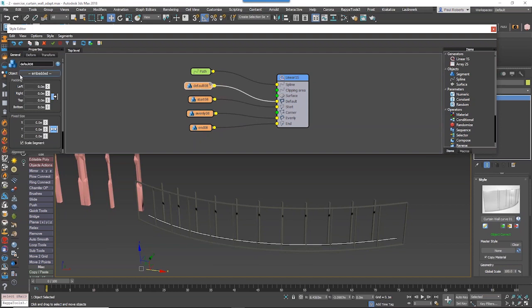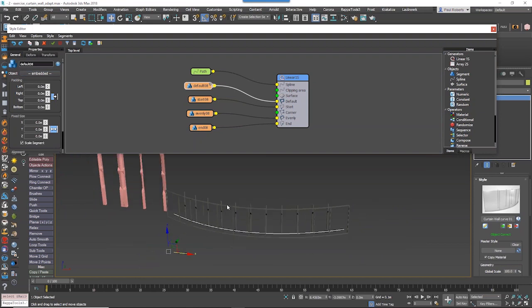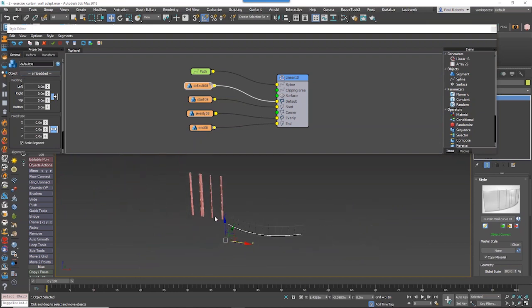And you see, if I click here and come over to the left here where it says object, this is where you'd normally pick the geometry from the scene, it says embedded. And that's because RailClone, unlike Forest Pack, doesn't need the geometry to remain in the scene. You can delete it, and RailClone stores a copy internally. You can also get this back out of RailClone, so you can edit it.